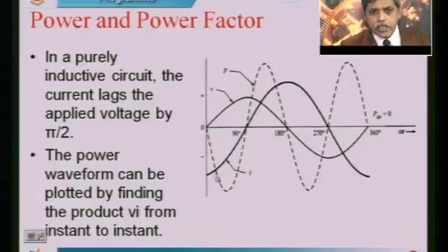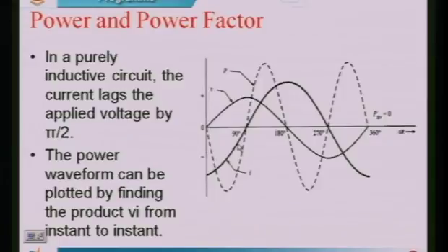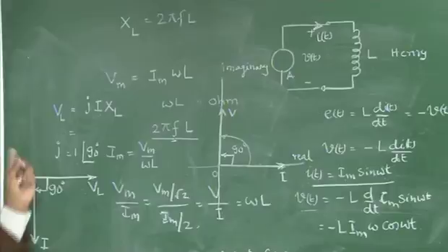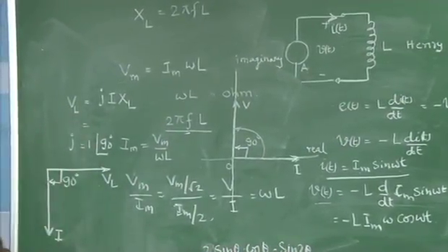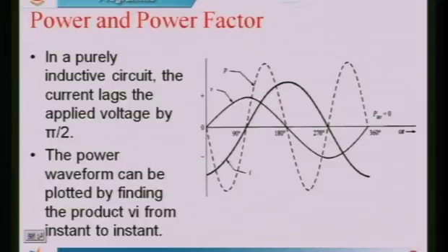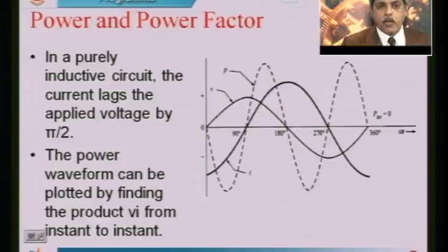See here, this is negative because the current is lagging behind. The phasor diagram I have drawn on the board will represent a different way here, because there I have taken the current as a reference. It is just the inverse of this. So either way you can represent it; to compute the average power, either that waveform or this waveform can be used.